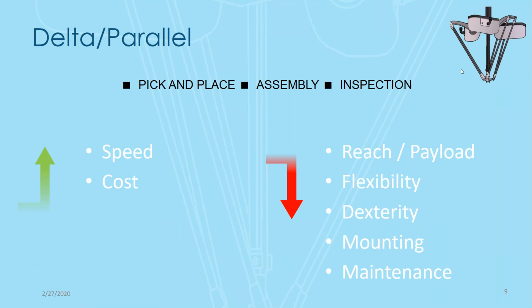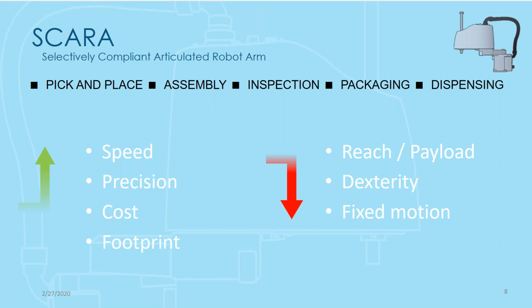Yeah, Matt, just to add real quickly on the SCARA robots. They're great for applications like screw driving or for pick and place. So you have very rapid, fast movement in the X and Y plane, and then you have that Z axis vertically. It's a rigid axis, but it's good for those types of applications I mentioned. And we'll get into some of those applications later on in my section.